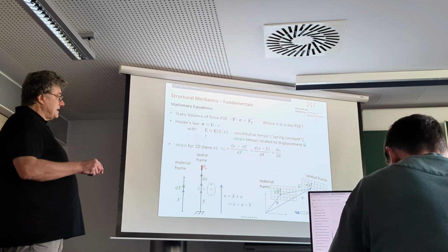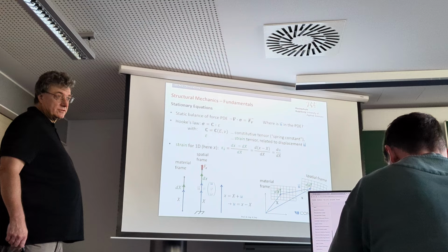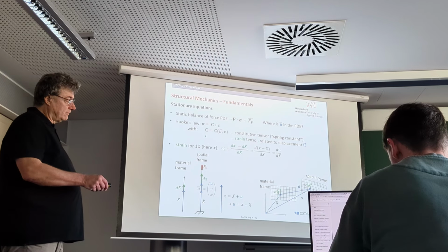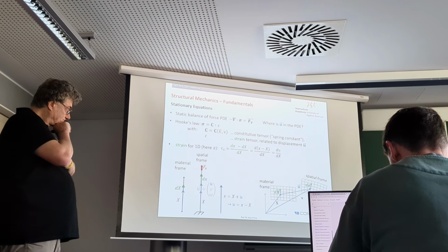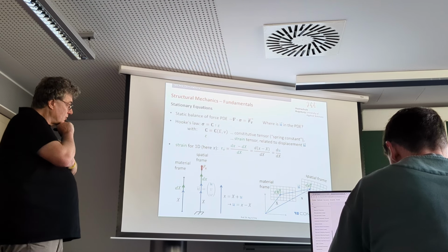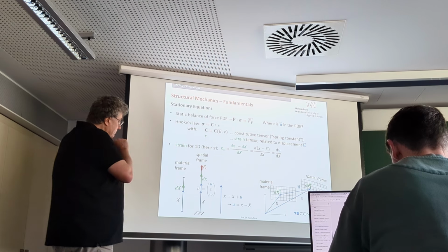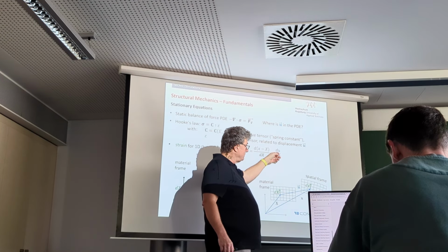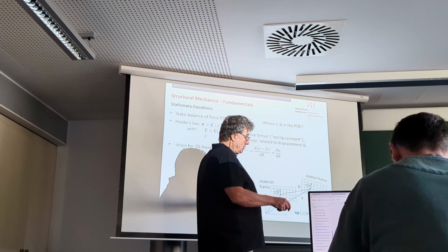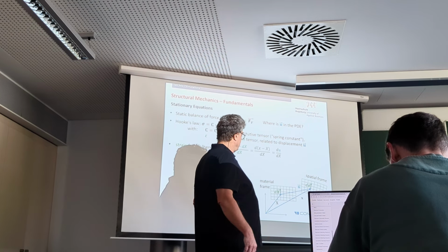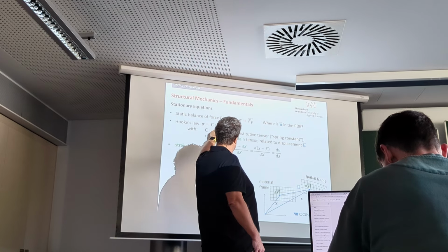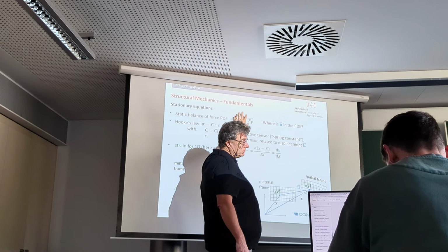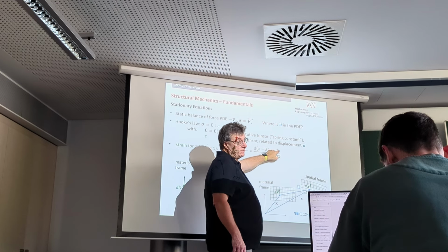Later we will see this is exactly what we call engineering strain. And as you saw with the example, that is not the whole story. That can cause problems, or will definitely in certain situations lead to very, very wrong results. I will come back to that result later on. So we have a derivative, we have the displacement, our main variable, which was temperature for heat problems and so on. From here it goes to strain, from strain it goes to stress, and then we are in the equation. So then that's an equation for the displacement.